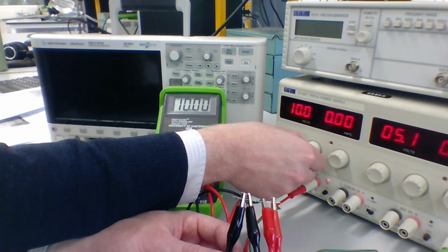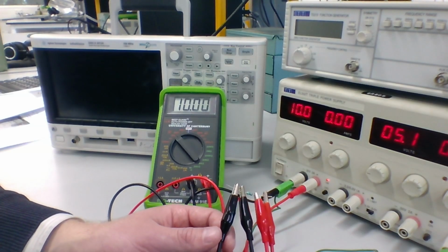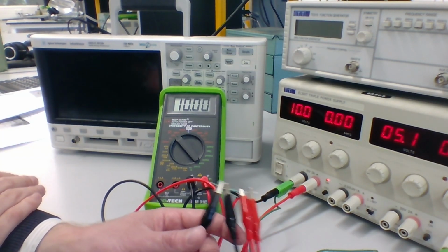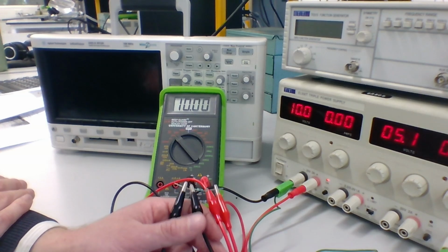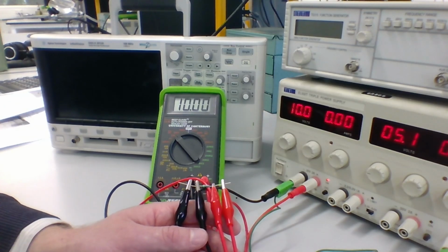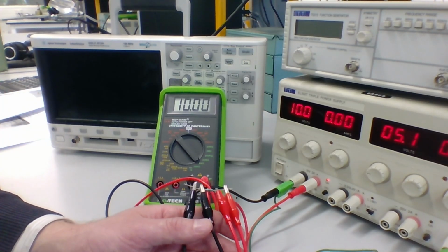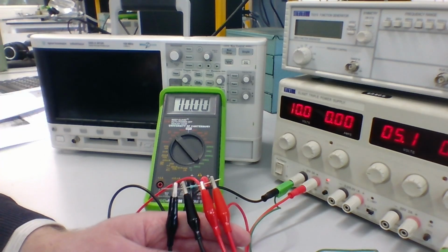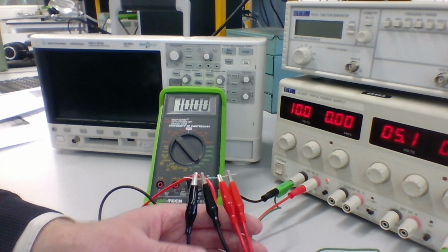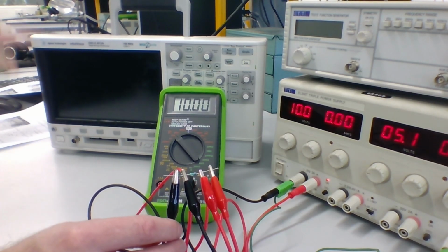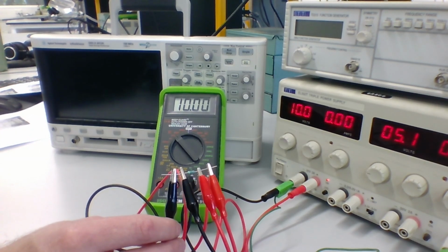Small adjustments like this can be okay if it's being measured or instrumented. Again, generally I avoid changing these while the circuit is live. So I'm getting 10 volts across this resistor. You should be getting close to 10 volts as well. It shouldn't be 9 or 11 volts. If it's 9.8, 9.9 or 10.1, 10.2, that'll be close enough for this lab. What matters here is that we're consistent with our measurements and calculations. Okay, so I have now measured 10 volts across this resistor. We can then, as the next task in the lab states, calculate the current flowing through the resistor using Ohm's law.